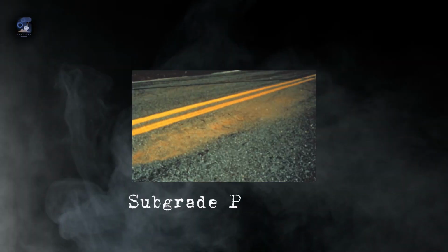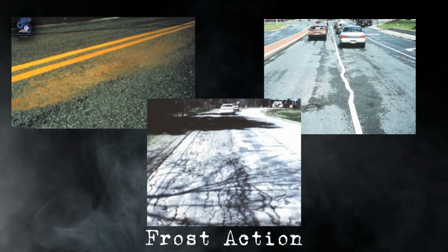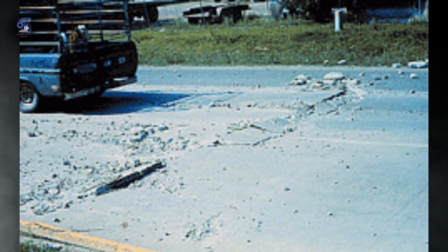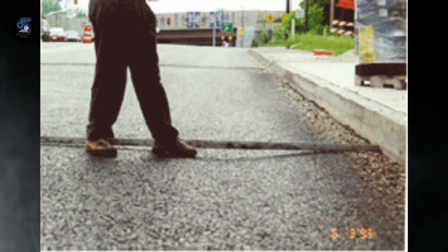We have water-related failures like subgrade pumping, drainage problems, and frost action. In other cases, it will be soil-related failures due to the presence of swelling soils, collapsible soils, karst conditions, or even liquefaction-susceptible soils. And lastly, the differential settlement failure.